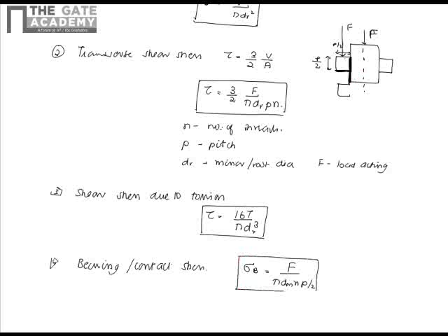So these are the different types of stress which come in the power screw. When we go for designing a power screw, we can see these stresses and find the resultant stress by means of the principal stress theory.